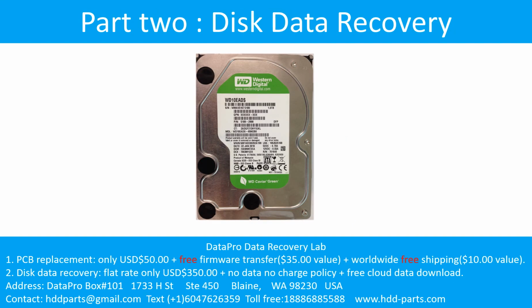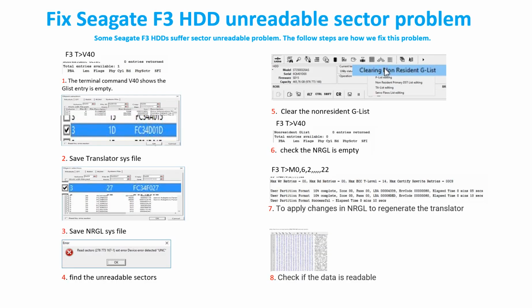Part 2. Disk Data Recovery. Fix Seagate F3 architecture hard drive unreadable sector problem. Some Seagate F3 architecture hard drives suffer from the sector unreadable problem. The following steps are how we fix this problem.